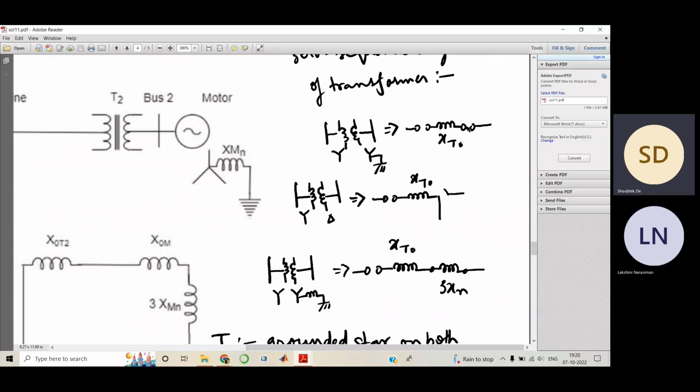See, basically, suppose you have this thing open. So if this thing was reversed, this would have been short, this would have been open. As a result, the net impedance on the left hand side would have a certain value, and on the right hand side it would be infinity, because the circuit is open. If you had an extended power system network on the right hand side, suppose a transmission line, then another transformer, then a load, a synchronous motor, you have every zero sequence reactance present there, and you are trying to find the net impedance.